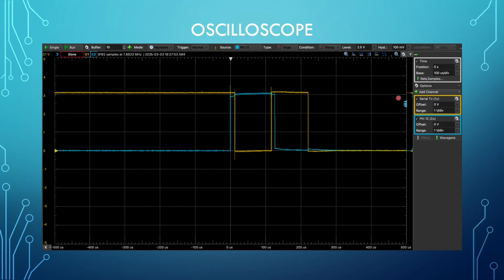So once we've exceeded 2.5 volts, then we send a trigger to the waveform generator to drop the power. If the power glitch was successful, then you'd probably see some fluctuations here on pin 12, but it would stay high because we would enter that infinite loop in the authenticated code section. If it drops, then we've bypassed that and we're back in the normal code loop where the access was denied.